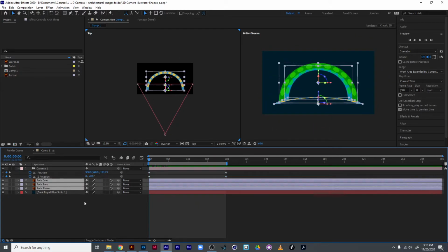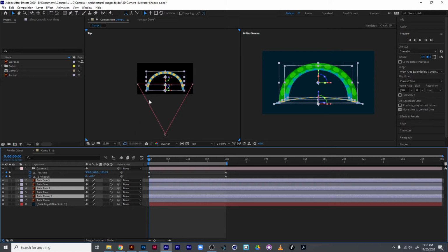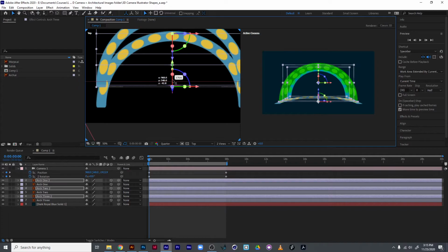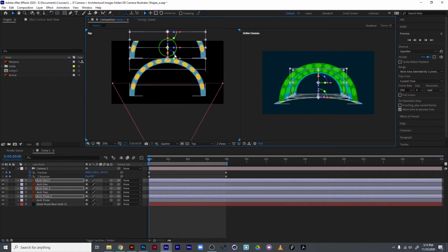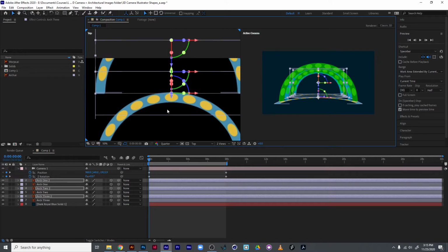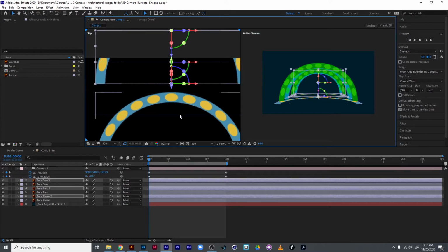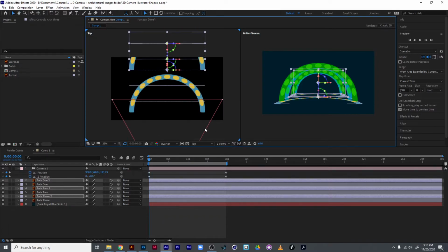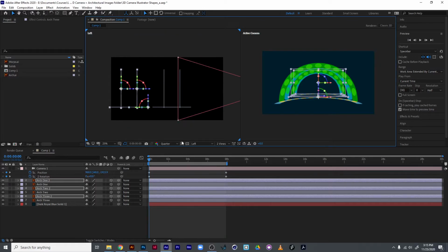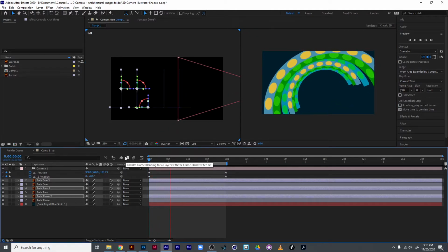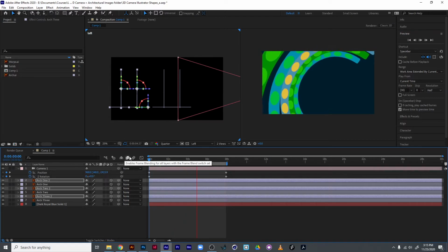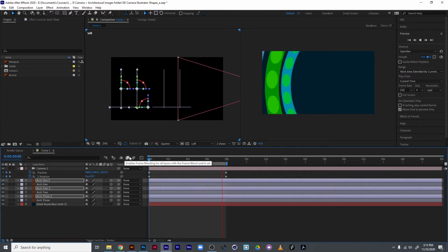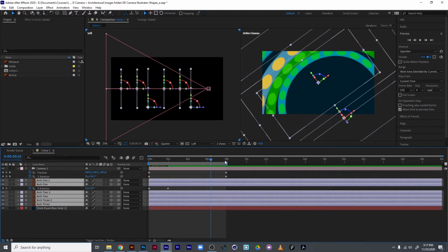Then maybe I want all of these to be duplicated and then set back a little bit more, so we get a longer sort of chain happening. And I'm pressing the middle mouse button to be able to click and drag, or you can hold down spacebar and use the hand tool to move around. If you want to see these from the side, just change it on where it says top and go to the left view, and that'll show us the side panel here as well. So now as this rotates through, now we've gotten something a little bit more, because there's actually something we can see, there's a little bit more reference. So now we're coming in through here, right?